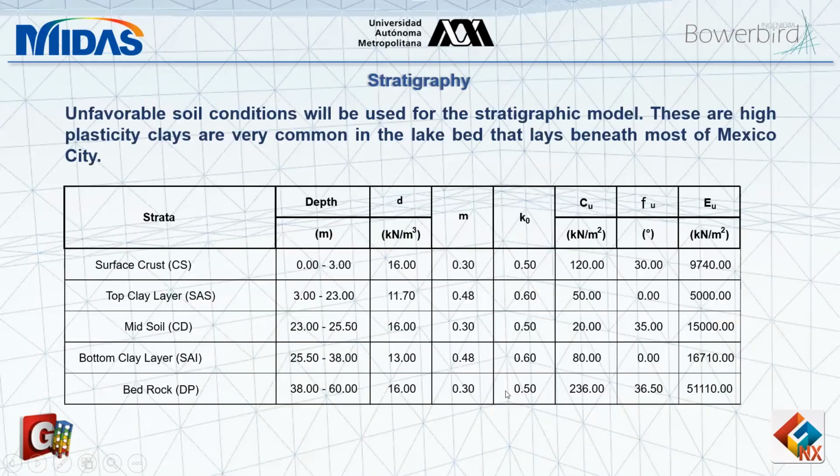In our case, we have manually imported these strata layer values. So we see we have the 5 soil layers, and these are the input values that we would be defining: your cohesion, your friction angle, your elastic modulus, your K-naught value and such. Having gone through these, either import from Excel or manually defining these values, we would then be ready to start the process of combining the structure with the 3D terrain